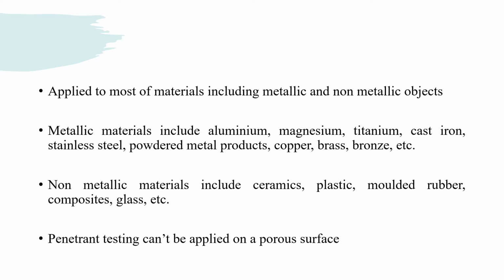So penetrant testing cannot be applied on a porous surface. This is the main disadvantage, that penetrant testing cannot be applied on a porous surface. Porous surface means a surface which allows the passing through of water, liquid or vapor.